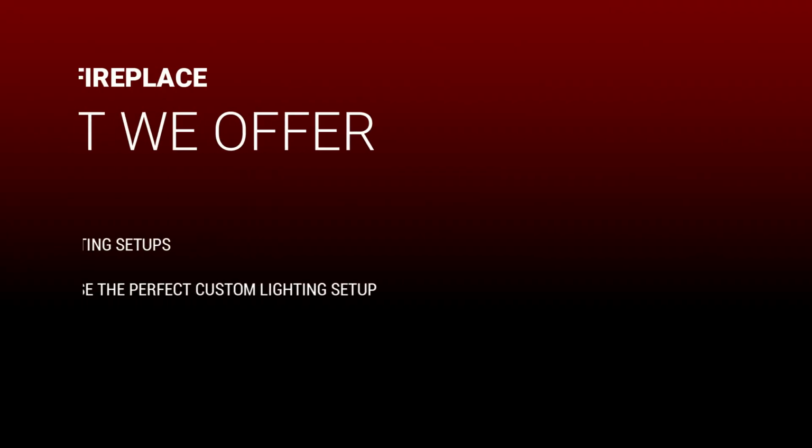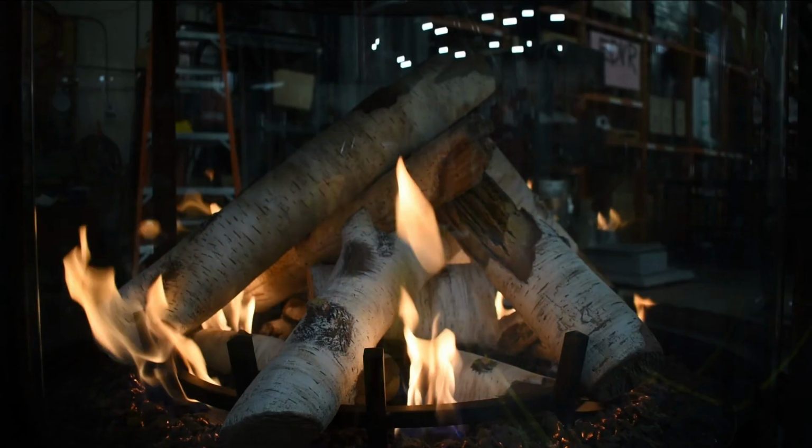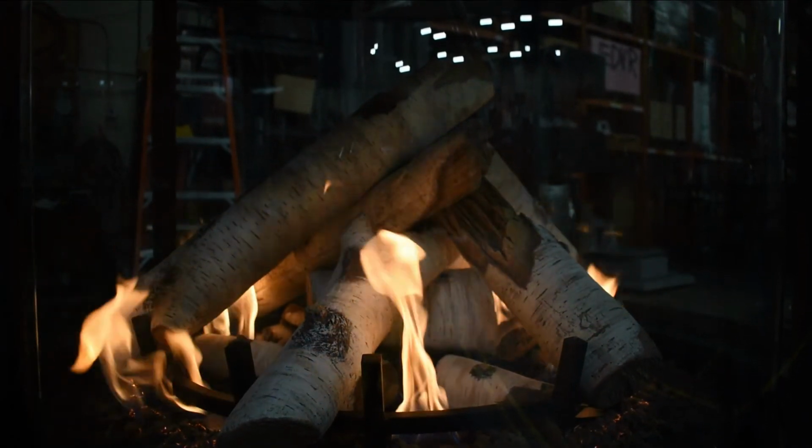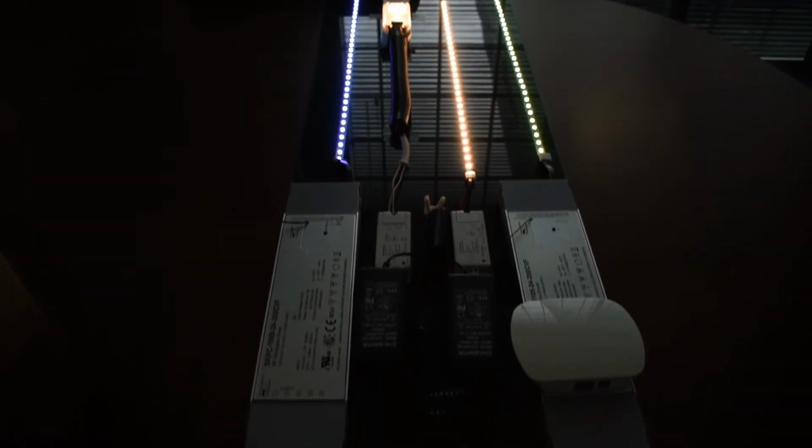All of the available options can get quite confusing at times, so in this part of the video, I'm going to go over a few standout examples of setups and their requirements. A standout example is connecting both a single color, single channel LED strip to an RGB multi-channel LED strip. It is important to note that only radio frequency connectivity can support multi-channel LED lighting. It is also important to consider the maximum recommended length of LED strip that the driver can support.